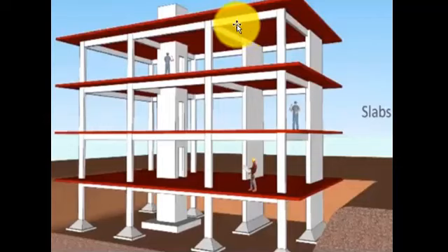The interior decorator wants to put some designs, like the POP and the ceilings. If the thickness of the beam is too much, it may limit the scope of the design, and the interior decorator may get stuck with the drop beams. So that's number one disadvantage. Another is they are only ideal for shorter spans.